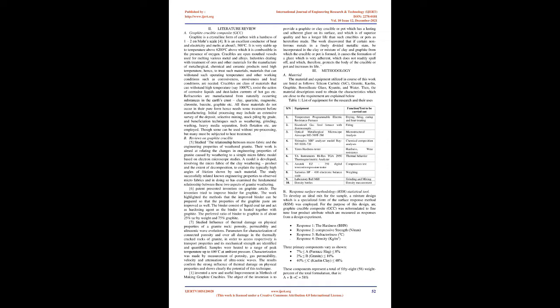Although from history, crucibles are usually produced using granite and clay, they can still be made from other materials that withstand temperatures high enough to melt the material they contain. Graphite crucibles are ideal for melting aluminum, copper, and other metals. Materials required for the production of crucibles include binder and clay material. However, crucibles can also be produced from composite materials. This involves variation in the percentage that constitutes the clay and graphite portion of the production process.